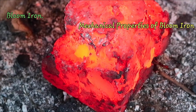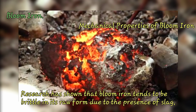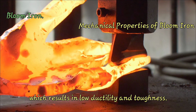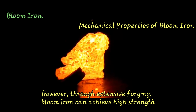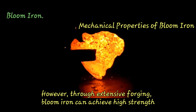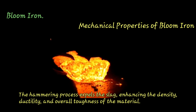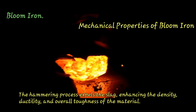Mechanical properties of bloom iron. Research has shown that bloom iron tends to be brittle in its raw form due to the presence of slag, which results in low ductility and toughness. However, through extensive forging, bloom iron can achieve high strength, comparable to that of hardened steel. The hammering process expels the slag, enhancing the density, ductility, and overall toughness of the material.